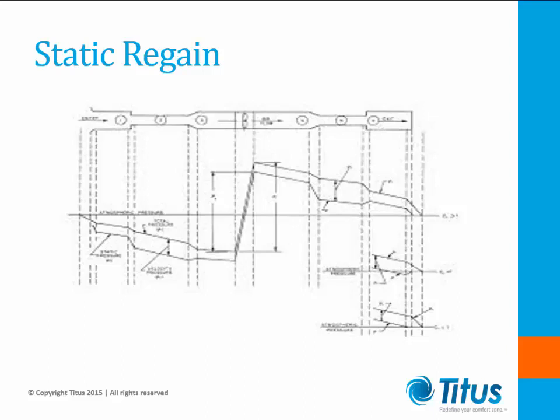Such spaces would be athletic stadiums, airports, and conference centers. Regain is regularly used, though, in risers, as the higher velocities allowed inside enclosed chases have adequate energy to be worth the duct cost. The enclosures help to maintain acoustic requirements and keep sound generation from reaching the occupants. Industrial installations generally do not have as stringent sound requirements. This allows for the use of the higher duct velocities that make the static regain design method the choice.